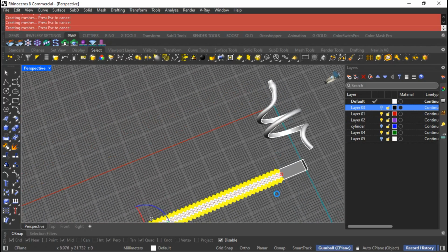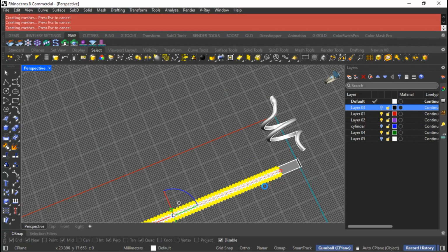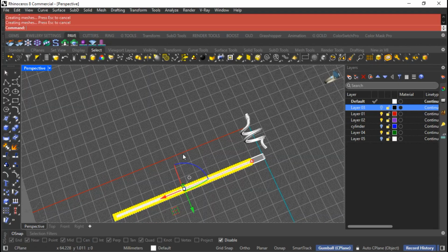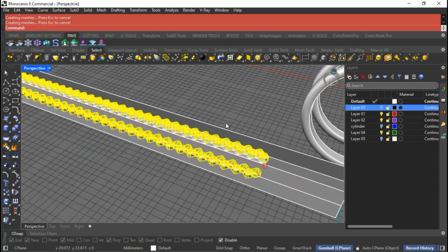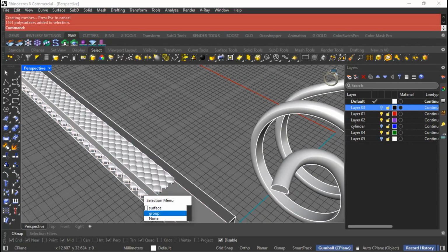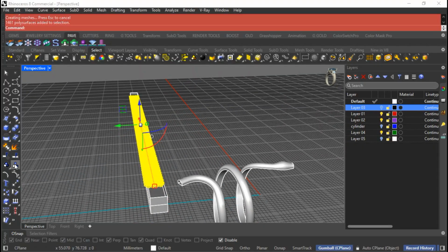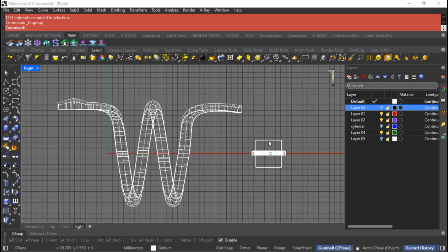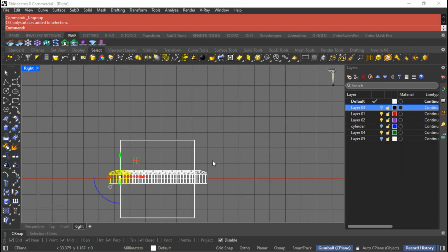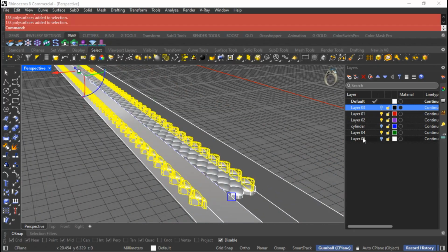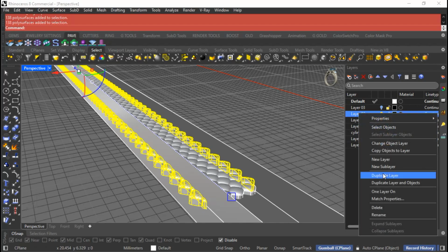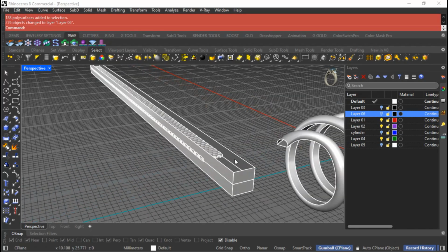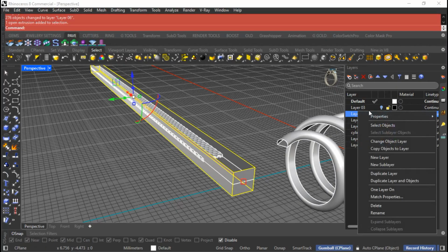And now go to front or right view. You can easily select the cut objects. Okay, this is done. Now let's go to front or right view. Ungroup them all to select. Okay, this is not good. Yeah, this is the perfect view. Now using this selection window, you can select the objects and move them to another layer. You can also rename the layer, but for right now that's fine. Now also select this surface and move it to the same layer.